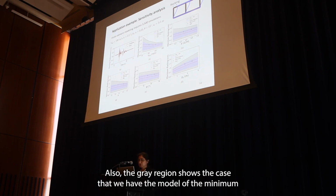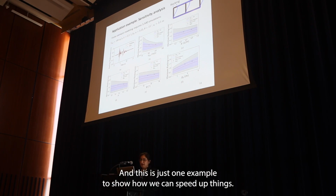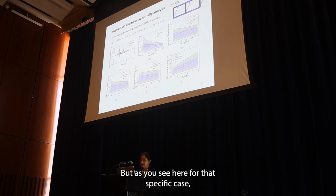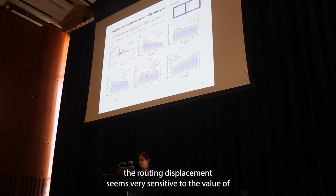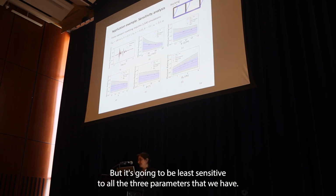Also, the gray region shows the envelope of the minimum and maximum racking displacement, considering all cases that we have. And this is just one example to show how we can speed up things, but as you see here, for that specific case, the racking displacement seems very sensitive to the value of the shear wave velocity at the surface and also the burial depth, but it's going to be least sensitive to the other 3 parameters that we have.